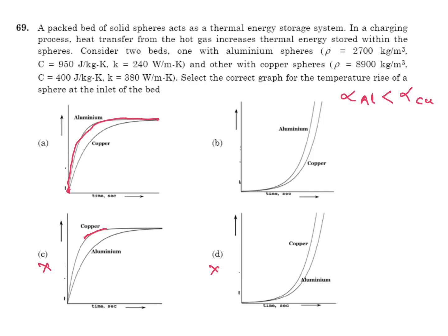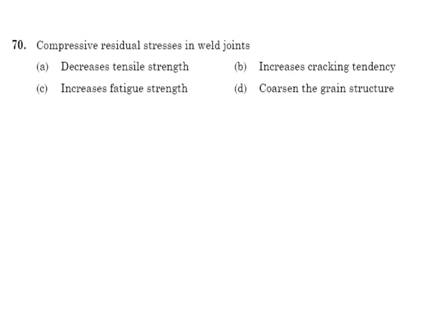A is the answer. Compressive residual stresses in weld joints decrease tensile strength, no. Increase cracking tendency, no. Increase fatigue strength, this is the answer. Sometimes after welding we give hammering. In hammering we are giving compressive residual stresses, so it increases fatigue strength.